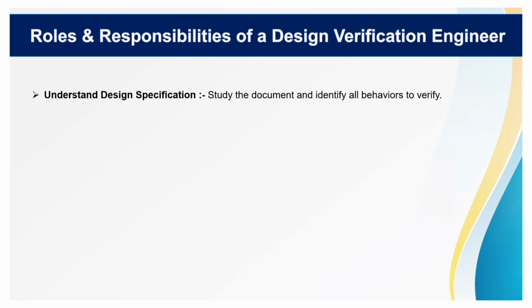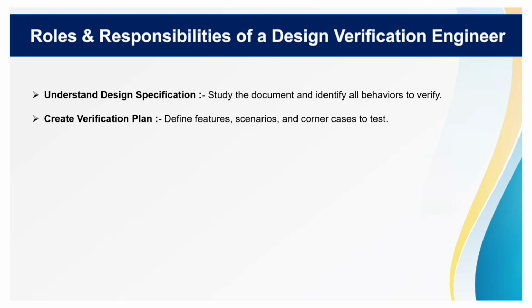Once the specification is clear, the next step is to create a verification plan. This plan defines what features need to be tested, which scenarios should be covered, and what corner cases must be verified. You can think of the verification plan as a roadmap that guides the entire verification process.